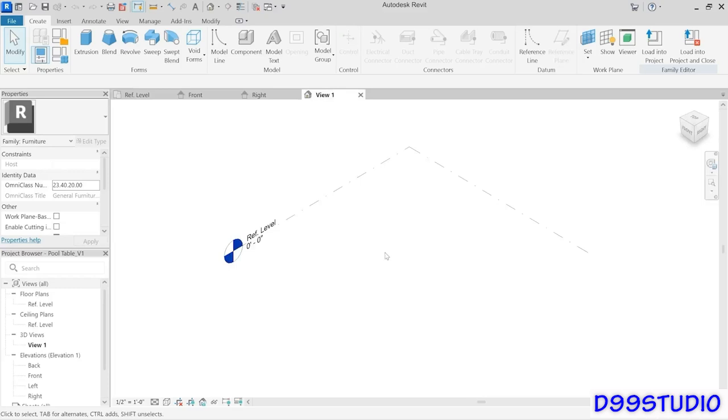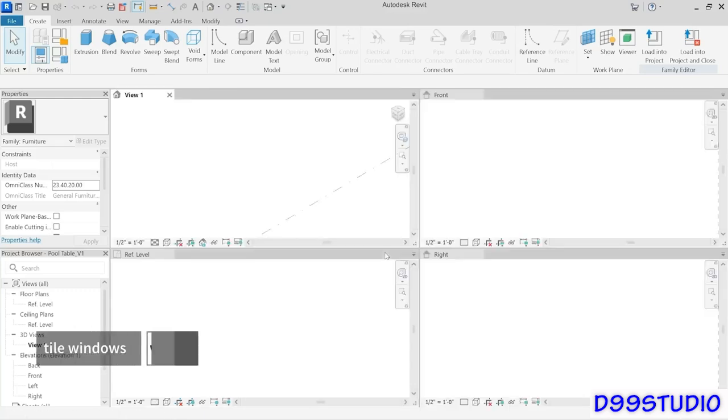So as you work through the family editor exercise, if you're closing and opening files, I just wanted you to be aware of that. If you're wondering why my files open up on screen with multiple tiled views and I'm able to just simply do WT and yours is coming in with only 1, it's because perhaps you clicked the little X here. So it's very important that you don't X out these views as you're closing. Just simply keep it tiled, save the file and close it, and you should be good to go.